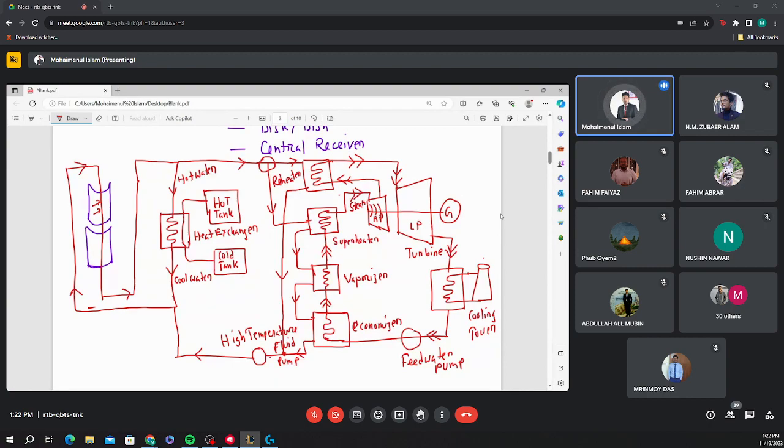It can receive the heat from that water in this reheater. And the reheater is actually a heat exchanger, right? So that water has heat, you have less heat. So you are collecting the heat from that water through this pipe, and again you are gaining the temperature which is required to run the low pressure turbine. That's how it works. Okay.